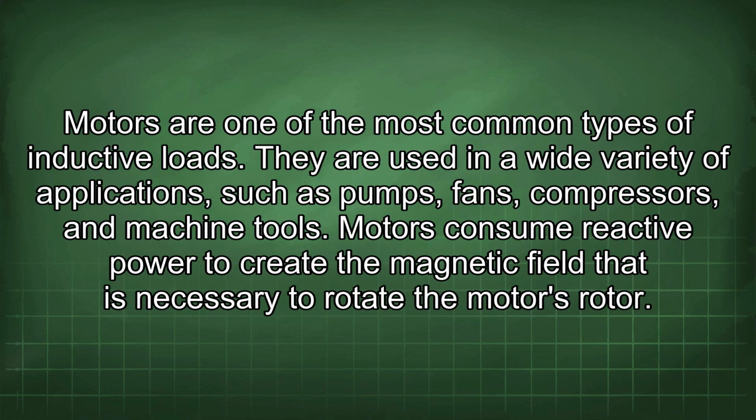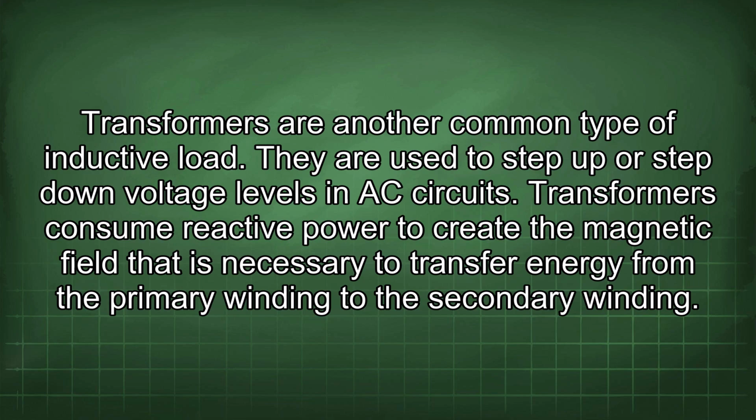Motors are one of the most common types of inductive loads. They are used in a wide variety of applications such as pumps, fans, compressors, and machine tools. Motors consume reactive power to create the magnetic field that is necessary to rotate the motor's rotor. Transformers are another common type of inductive load. They are used to step up or step down voltage levels in AC circuits.